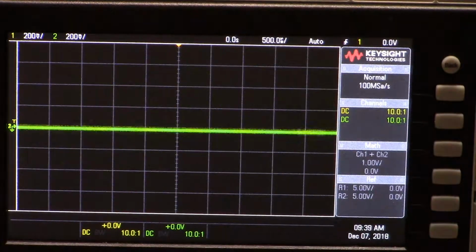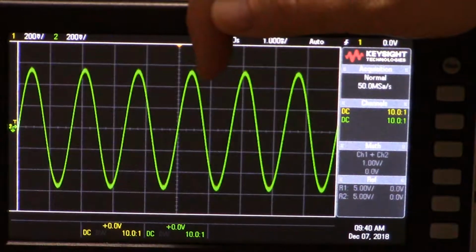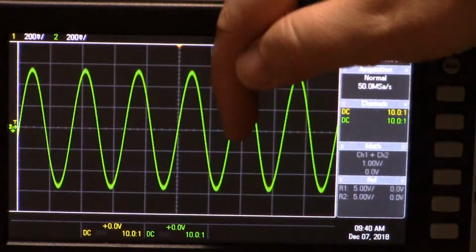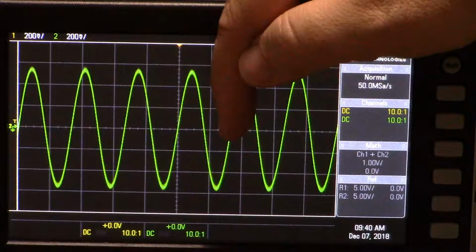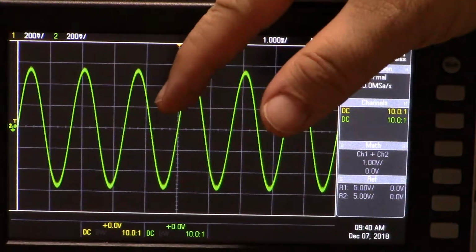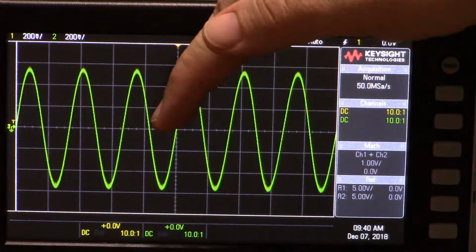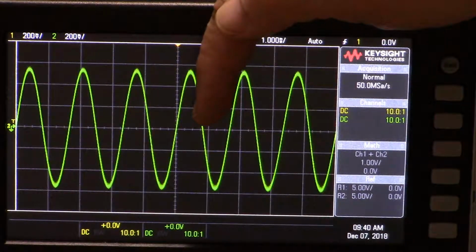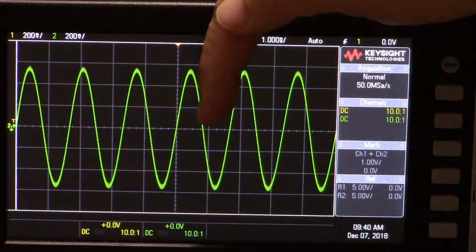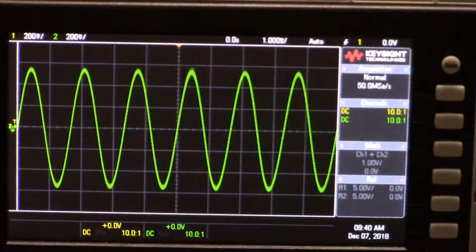So right now, if I have 1 millisecond dividers, then it is 1 millisecond to about 1.5, 1.6, about 1.6 milliseconds from the start of a wave to the start of another wave, which is about right because 60 hertz, I've memorized this value because of programming, 60 hertz is about 16.67 milliseconds. So 600 hertz would be about 1.67. So there's our 600 hertz frequency.